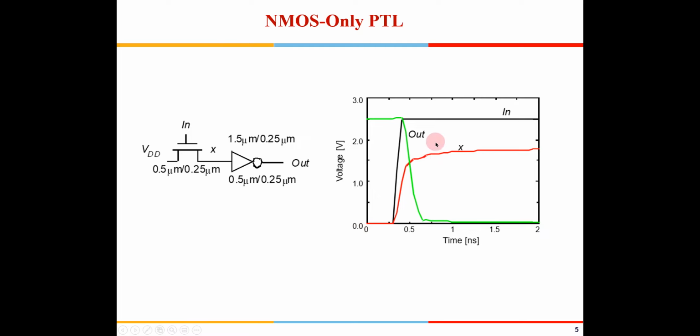If you see here, right? So unless you have an inverter, also the inverter is a simple static circuit. Simple static inverter, right? So to restore the levels finally after the pass transistor logics, we might have to use one inverter. Okay, so then it will get restored, because when we are using pass transistor, it won't be rail to rail voltage.